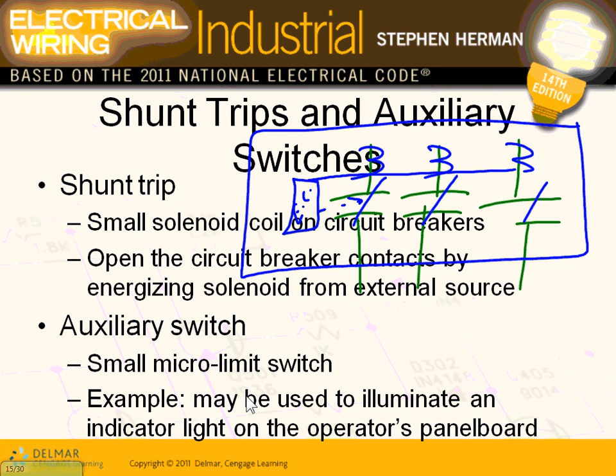What they do with electronic circuit breakers or even thermomagnetic circuit breakers, guys, is they have a shunt trip. You know what that is? They have a little coil here that they can externally energize to trip the circuit breaker. So I can put 120 across this coil and trip the circuit breaker from my laptop. They call it shunt trip. Remember the PDUs that we looked at yesterday? By code, they require a shunt trip on every main.